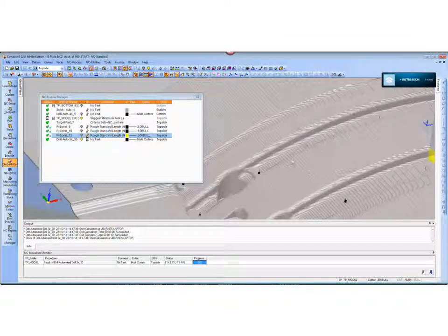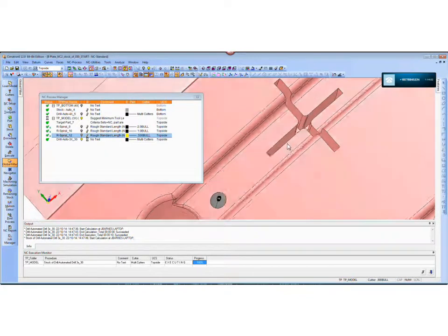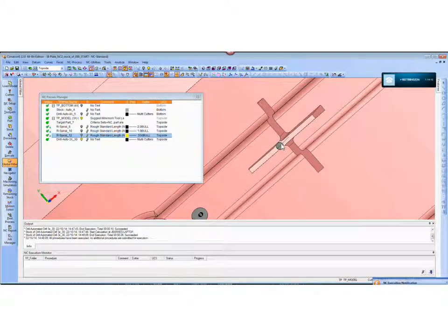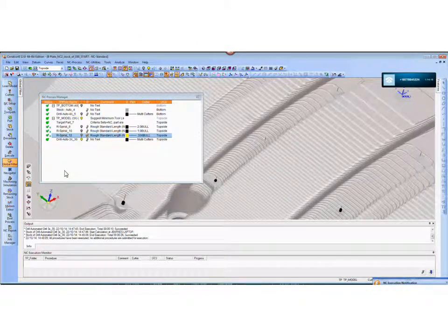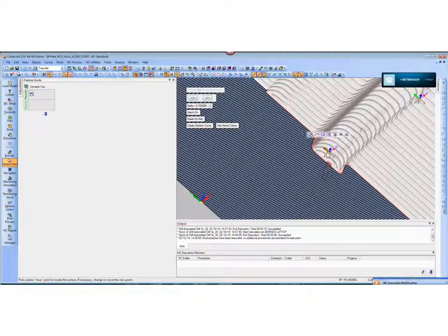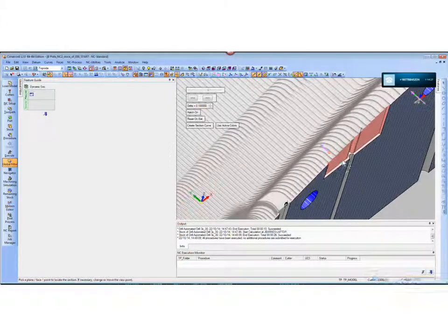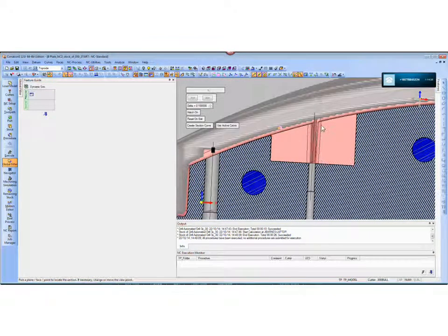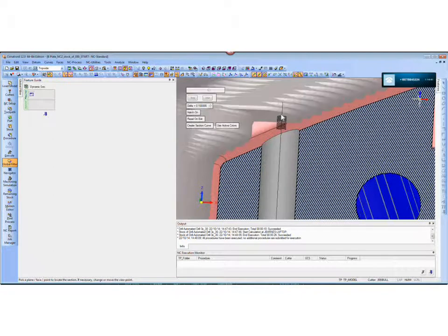Over here, you'll see that I've got an ejector pin hole at the bottom of this rib. So it's way down here. And even so, if I tell it to start the drilling process at the stock, let's do this. Okay, so the top of the hole is here, but it knows to start at the stock, and it starts up here. Same thing with the circle milling. You can see how I left that little flat there. I run this down, establish a flat, and then I can do the drilling operation after the circle milling.